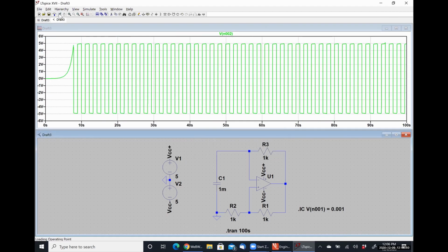Now it takes a little bit of time to swing up, right? So I'm just kick-starting the energy, is all that's happening there. And the smaller the voltage I apply across the capacitor, the longer it's going to take for the feedback to ramp up and make it swing. That's all that's happening. When we start with a low amount of energy stored in the capacitor, it takes time for it to cycle back and forth until we get that cascading positive feedback that causes it to go rail to rail. All right, so